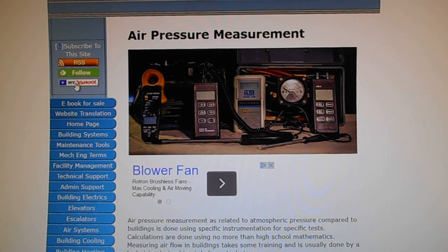Before increasing pulley size, you must be certain that the horsepower of the motor is great enough. If it is not, you will then require that motor be replaced with one of a greater horsepower and current draw capability. Technicians, after setting the correct air system air volume, are then required to adjust zone balance dampers to increase or decrease zone supply and return air to meet design criteria.